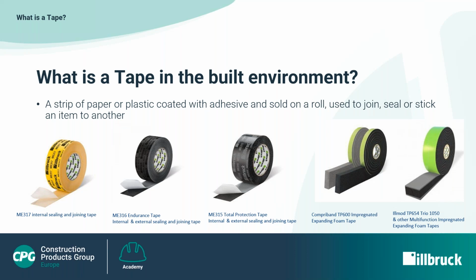In the built environment, tapes are almost always backed with a high-strength water or moisture-resistant self-adhesive. Tapes do not require a separate adhesive before they can be applied. Once applied, tapes are left permanently in situ and will last as long as the building or the substrate to which they are applied. In the context of the built environment, tapes are restricted to a maximum width of 150 millimeters. Applications requiring a sealing solution above 150 millimeters would normally require a membrane as an alternative.